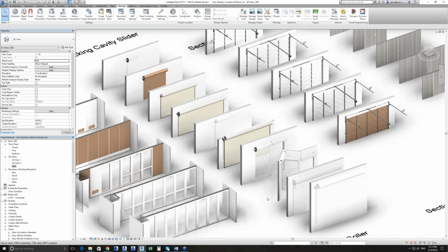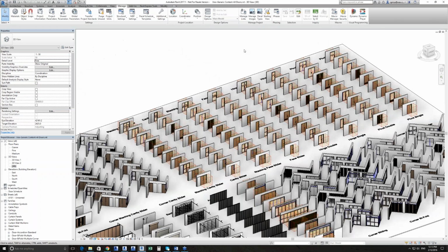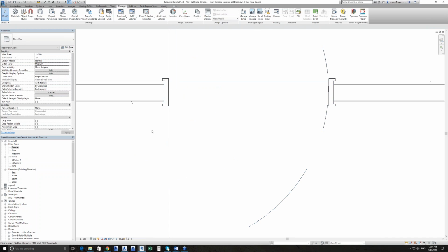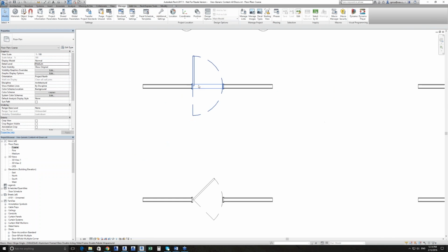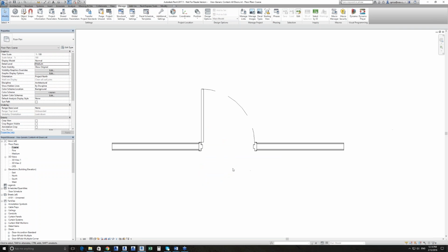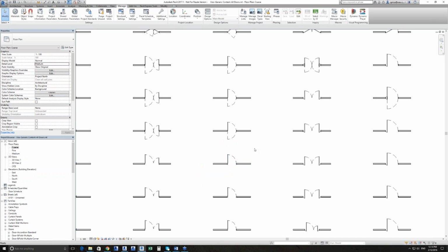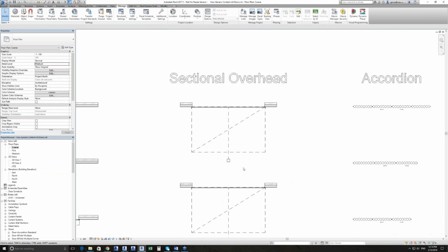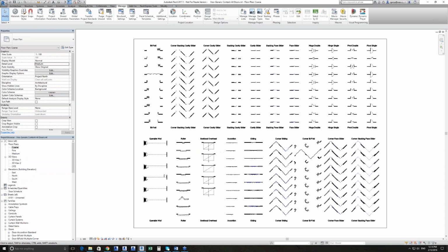So similarly, if I go back to my plan view, just so you can see the differences when I cycle through these, let's look at the hinge door, for example. I'm going to switch that to medium, so we can start getting the frame detail showing up, depending on what type of frame it is. And at fine detail in plan, there's no difference from medium. It's the same representation because hardware is not visible in plan anyway. You'll see a lot of the stuff is dashed overhead automatically, so we can make sure we get the clearances and things like that.